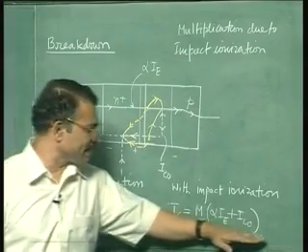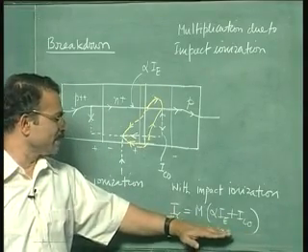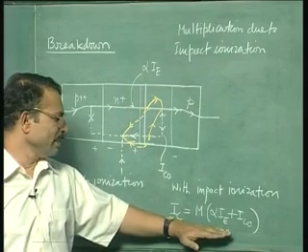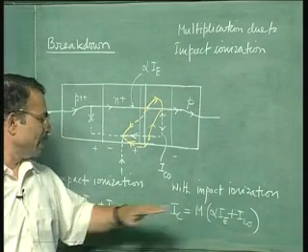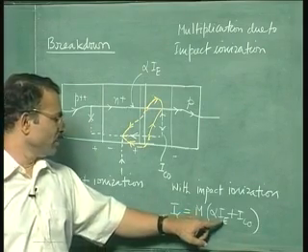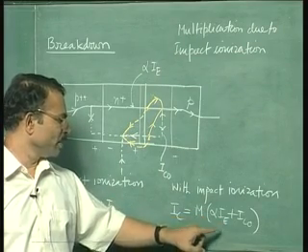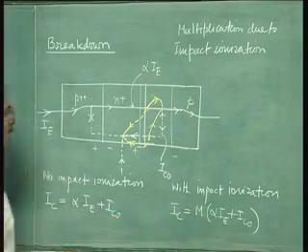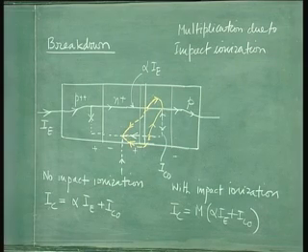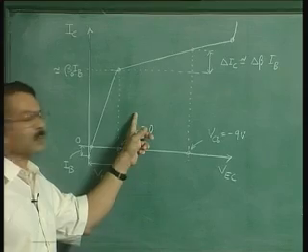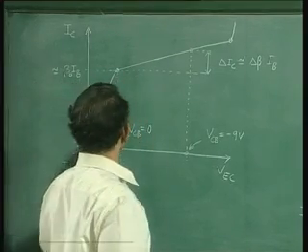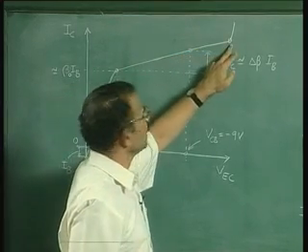Now when we write this equation, you can easily transform it to show when the collector current will start increasing rapidly. For this purpose, we must write IE in terms of IC and IB, because IB is being maintained constant. You can see here that when you are tracing this whole curve, your IB is constant.